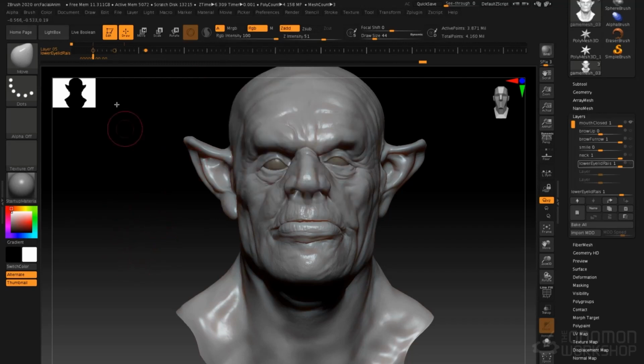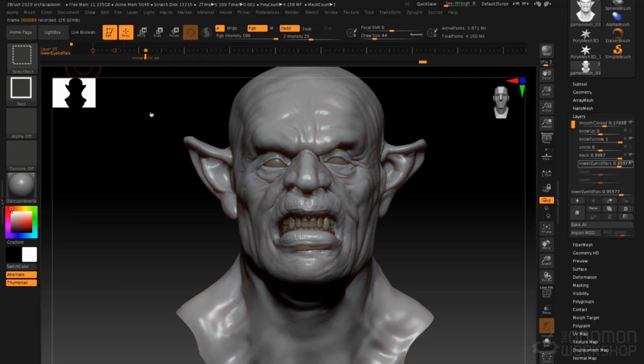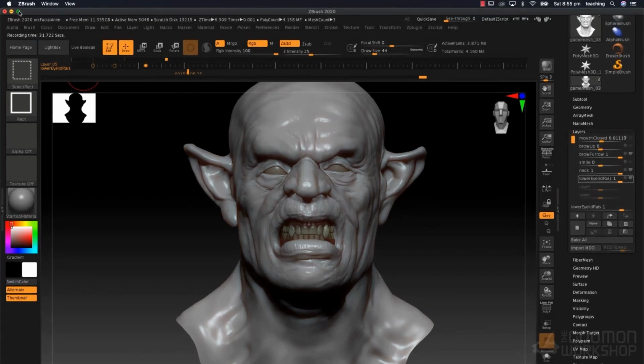So to render that, Control, Shift, click under the timeline, and it will start to go through each frame. There we go. You can see it's recording the frames now. That is Control Shift click under the timeline. Now it'll go through my keyframes here, and once I get past this last keyframe, I can actually escape out of the recording. There we go. We've reached the full extent of the animation. So we can just go ahead and hit the escape key.